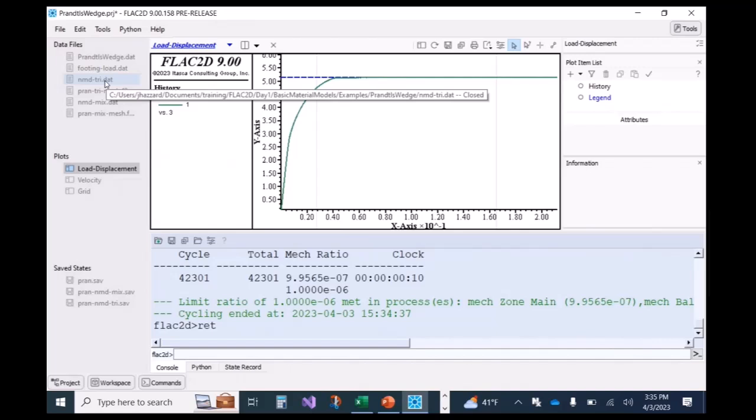These are the most accurate. Often, if you have really ugly geometries, you can't fill them up with four-sided zones. It's not always possible to do that. So you could fill anything with triangles. It's like a mathematical theorem. You can fill basically any shape with triangles, so you can always mesh with triangles.